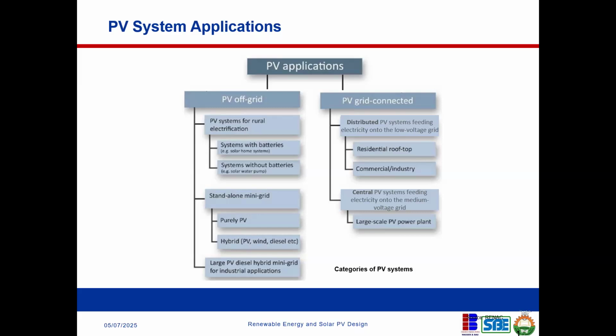However, at the design stage of the system, the sensitivity of the load has to be taken into account. If you have sensitive loads connected to such a system, because of the interruption when the grid fails, you need about 10 seconds to start up the generator and then connect it back. If you have sensitive load, it might become necessary to find a way to make sure that while that transfer is going on, the load is not interrupted.